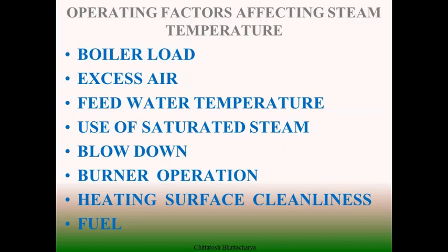Besides that, burner operation is an important parameter. We can arrange and operate the burner in such a way that we can manage the distribution of heat between superheaters, reheaters and water walls. If we want more heat to be absorbed in the water walls compared to superheaters, it can be done. So we have to see how the heat absorption is distributed with the burner operation, as that affects the steaming parameters.